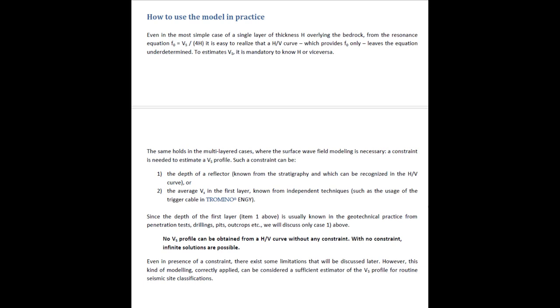Shown on the screen is a screenshot of the HVSR data modeling menu. Once we're satisfied with the quality of the trace, the next step is to interpret what these peak frequencies represent in the subsurface. In HVSR analysis, the dominant resonance frequency can often be correlated to the depth of a major impedance contrast, such as the interface between soil and bedrock.